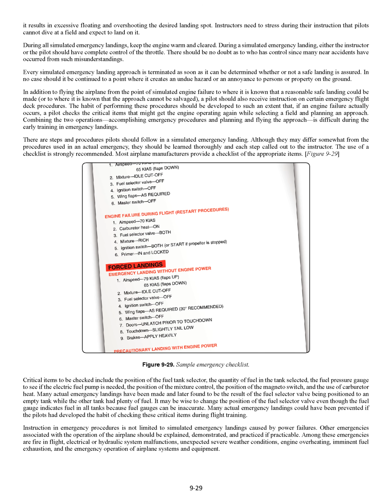during flight training. Instruction in emergency procedures is not limited to simulated emergency landings caused by power failures. Other emergencies associated with the operation of the airplane should be explained, demonstrated, and practiced if practicable. Among these emergencies are fire in flight, electrical or hydraulic system malfunctions, unexpected severe weather conditions, engine overheating, imminent fuel exhaustion, and the emergency operation of airplane systems and equipment.